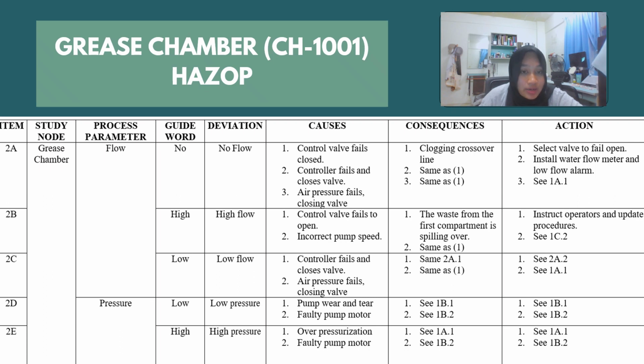and low flow alarm. And what if high flow? The control valve fails to open, and incorrect pump speed. So for these consequences, the wastewater from the first compartment is spilling over, and the action that we need to take is to instruct operators and update the procedures.